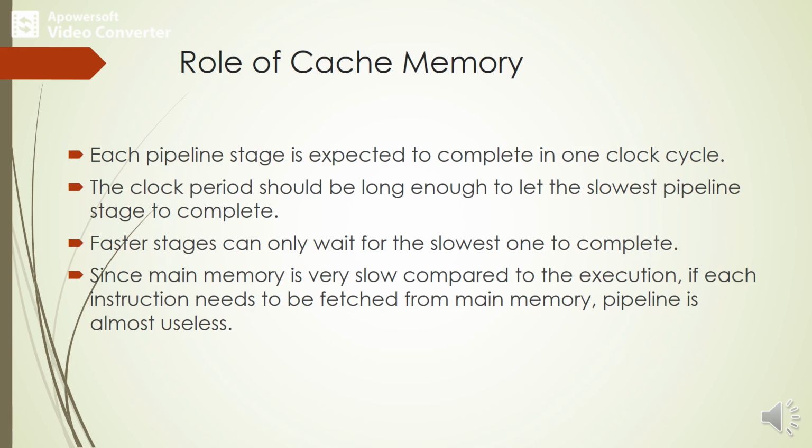If one clock period is required to execute one instruction, the clock cycle has to be equal to or greater than the time needed to complete the fetch phase. Suppose you have a set of instructions I1, I2, I3, I4 and so on, and some instruction requires longer time to complete. We still have to maintain a uniform clock cycle, so while choosing the clock cycle, we consider the task with the longest operation time.